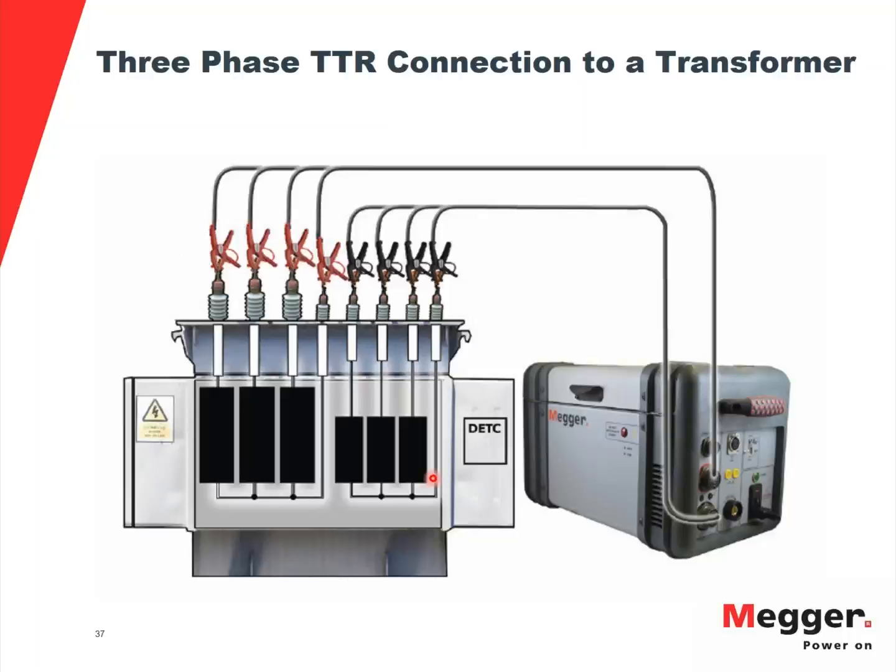I will try to answer this in two parts. One is from the TTR point of view. As we were talking about the voltage dependency, you would run into some voltage dependency because you have three windings, and for the winding farthest away from the core, which is the high voltage winding, the magnetic coupling might be different. So if you're doing a turns ratio test, you might run into some voltage dependency. So keep an eye on that.